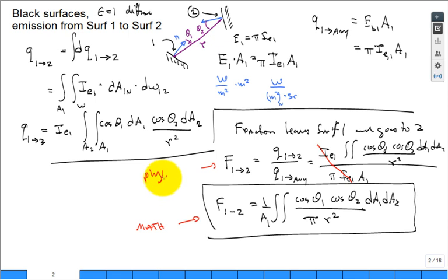So if I was doing a numeric simulation, I was randomly tracking photons leaving a surface 1, I would say, okay, I'm going to send out 1,000 or 100,000 or 1,000,000 photons, right? And then I'm going to see where they go, do a little numerical checking where they go. And then I'm going to tally up the ratio, and that's my view factor. It's a fraction. If I do the emission of the photons numerically from a surface correctly, I'll be able to get a pretty good estimate of that view factor.